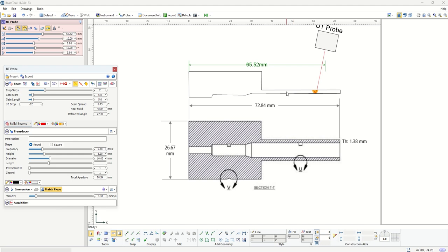If we treat all the surface-breaking features as sharp indications like notches, as drawn in this calibration piece, we know that typically angles between 35 and 58 degrees are best to interact with corners and see those kinds of sudden changes in the surface.